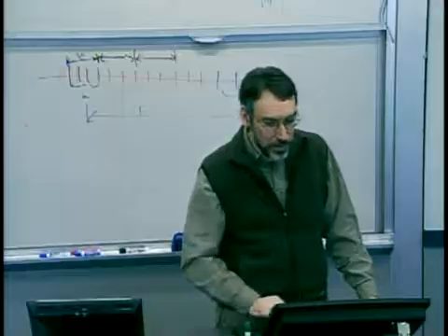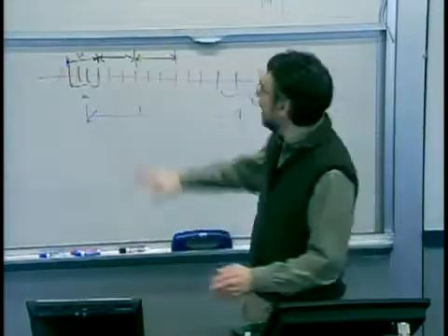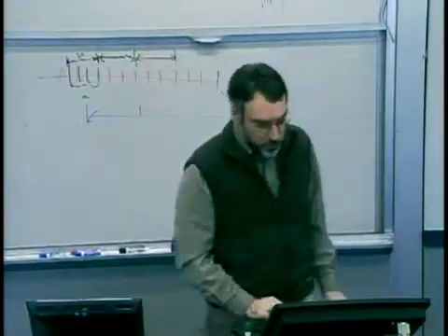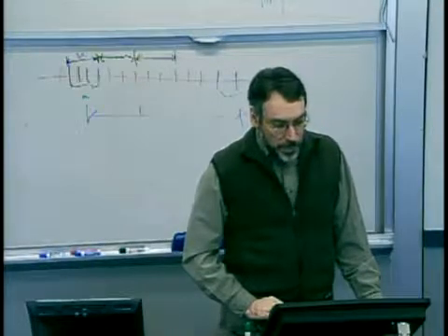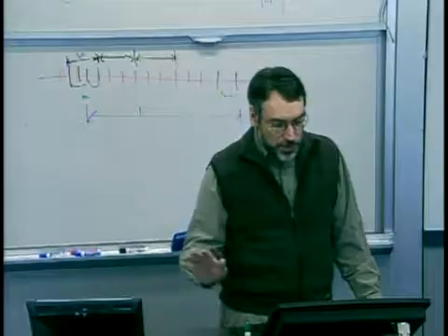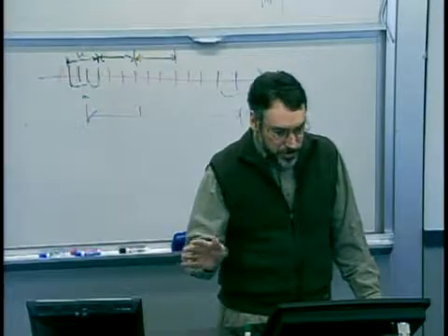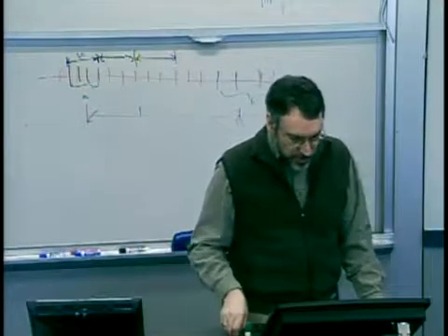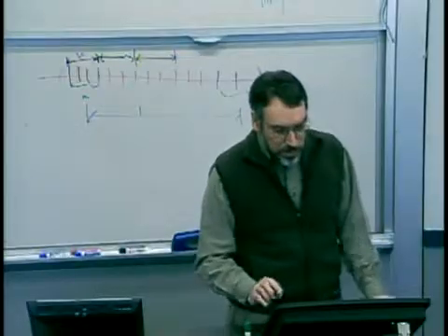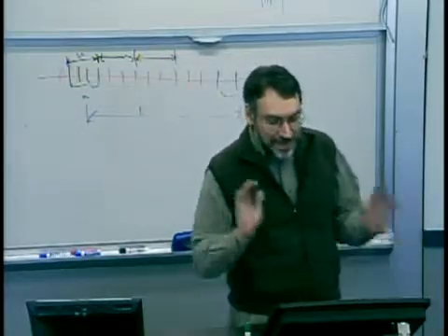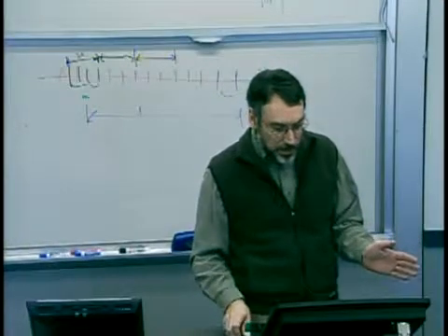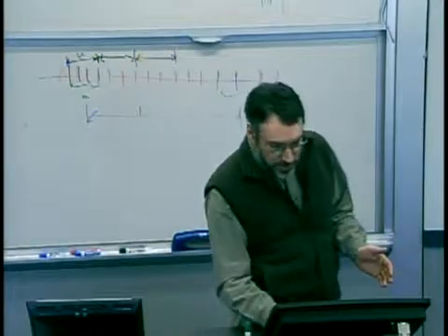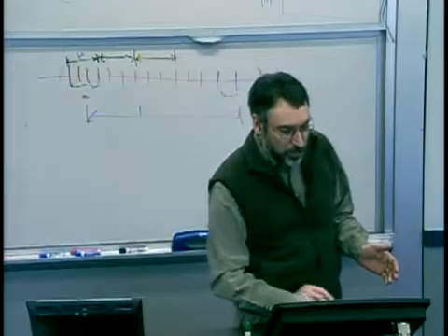So here's an example on the use of tolerances, now pulling in both our distributions and control charts. Here we're assuming the process is normal. What I've drawn here is, first off, our in-control process with its mean and its plus or minus 3 sigma points.